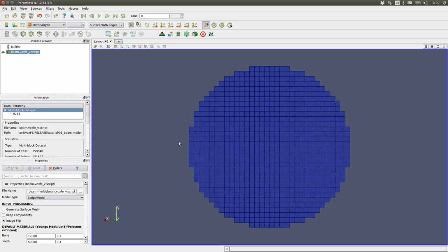And I want to constrain this face, but I want to do it in a way that is minimally impacting on the model. And the way to do that is to choose one point, let's say the central point here, which can't move, and another point here on the edge which can't move from side to side, and then constrain all the other points in the Z-axis so they can't move in or out of that plane. So I'll start with that middle point. We use our select button, and if I can find the middle point, maybe about there,